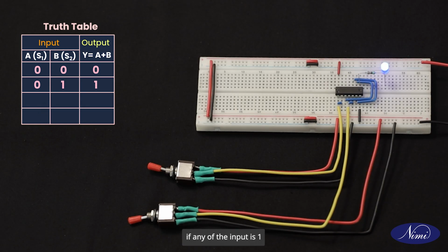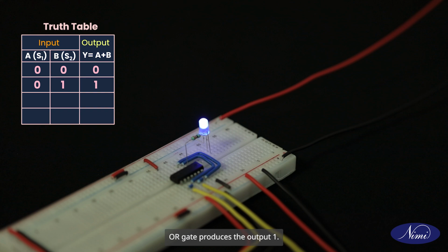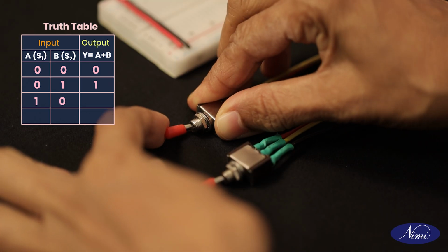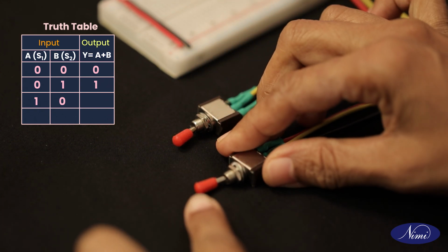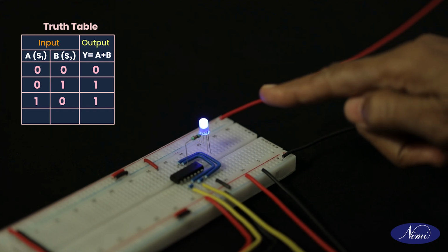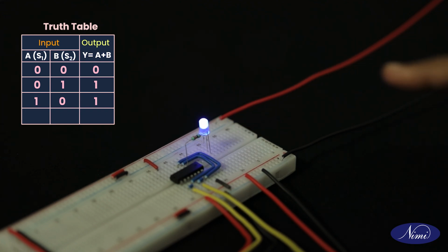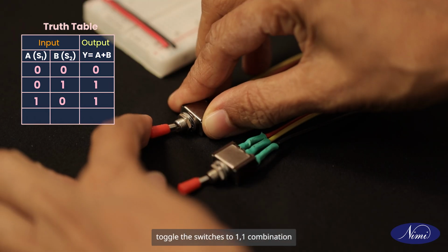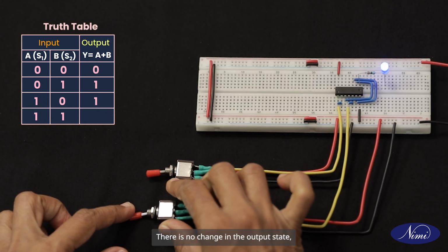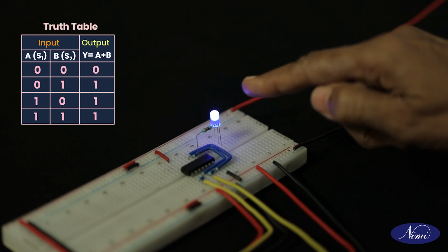So, we know that if any of the input is 1 or both are 1, OR gate produces the output 1. Now, toggle the switches to 1-0 combination. There is no change in the output state. The LED is glowing. Finally, toggle the switches to 1-1 combination. There is no change in the output state. The LED is glowing.